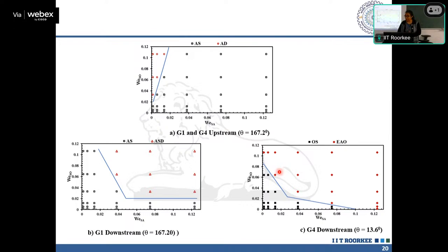Here we have organic phase slug and encapsulated aqueous slug. So this encapsulation is a new thing that we are seeing. This is a water droplet encapsulated inside the toluene one. So altogether a new flow regime has not only appeared but also occupied a dominating part of the flow pattern map. So this is what happened when you combine things together.